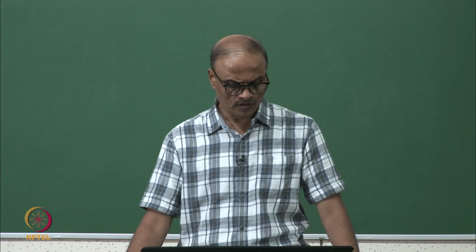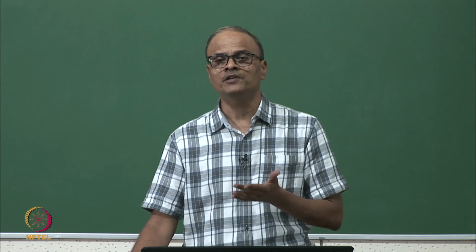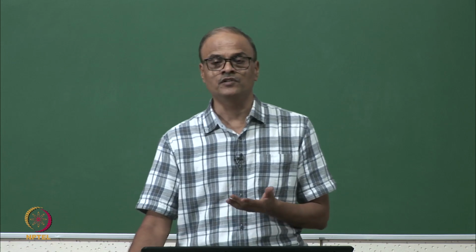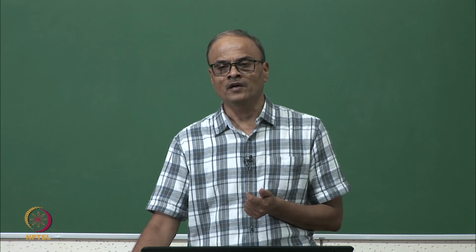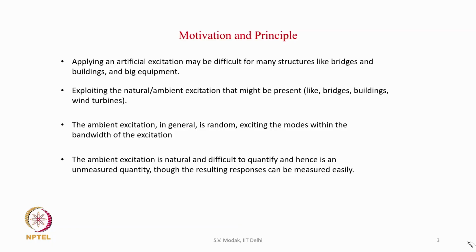Another observation is that the ambient excitation which is present in many of the structures is random in nature. So, these random excitations excite the modes which are within the bandwidth of the excitation, and therefore, the response contains the information about the model parameters.